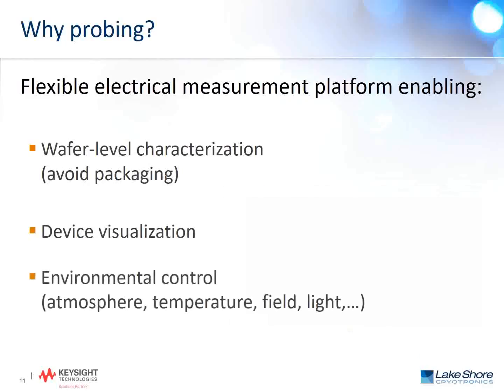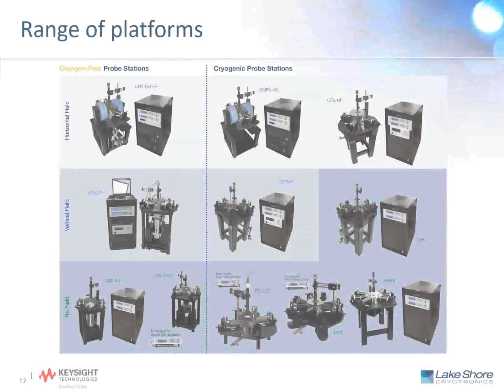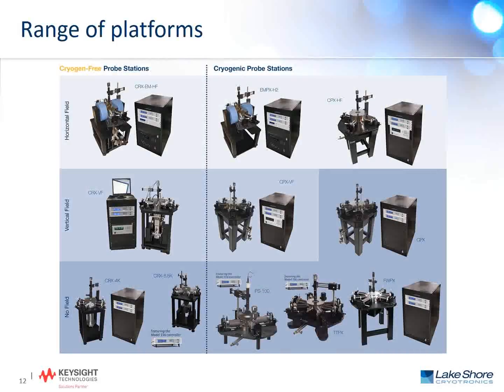Finally, researchers use probe stations because of the unparalleled flexibility for controlling the device environment during a measurement. Probe stations often can be configured to change, say, the surrounding atmosphere and/or temperature of the device, apply an oriented magnetic field to the device, or illuminate the device during measurement. Because environmental control is a key factor for device measurements, Lakeshore is offering a wide range of liquid cryogen as well as cryogen-free probe stations.